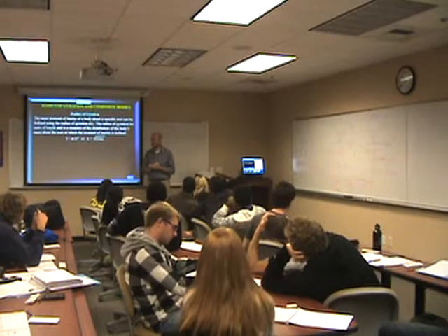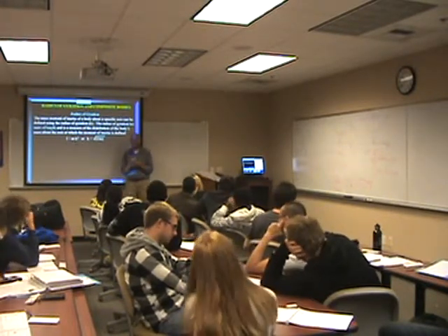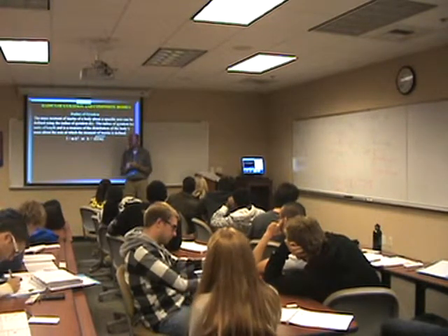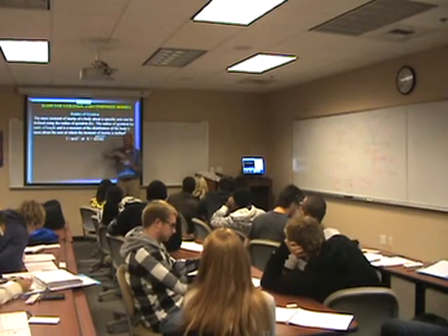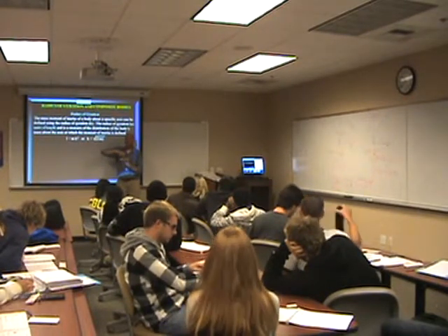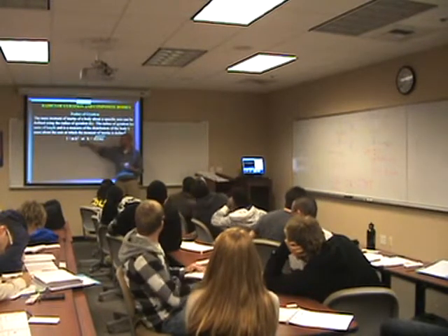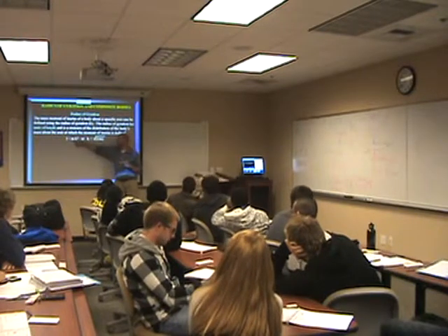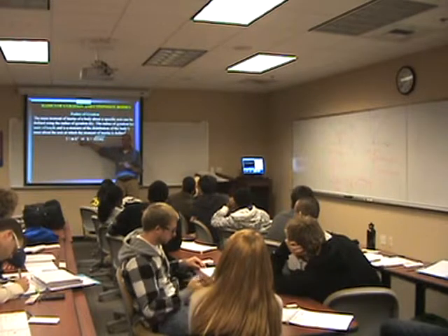That's how we do it by calculus. And what does this say? What we can do is replace this object with an object with the same mass at a distance k from its center. So put all of the mass of the object at a distance k, and it'll be just as hard to rotate. Conceptually the same. It's just as hard to rotate with all the mass distributed as it is if you put all of your mass at a distance k, the radius of gyration, from the origin.